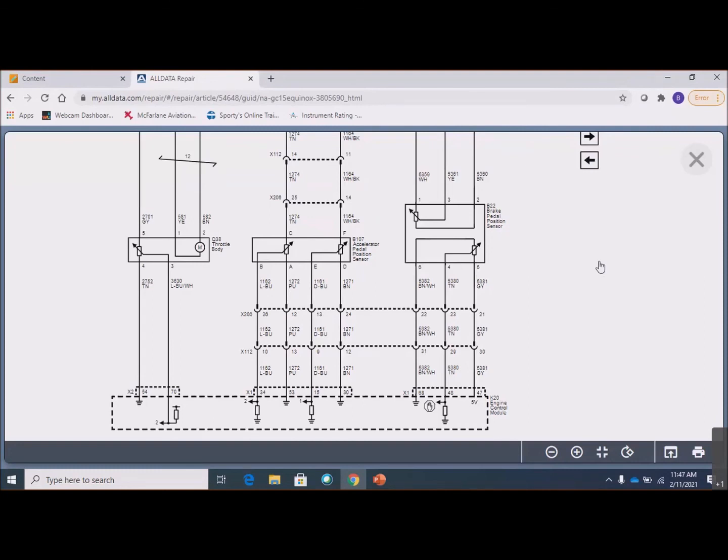It won't do anything. Or maybe if you're the customer, if you're the driver, and this thing goes bad while you're going along the road, maybe you have enough engine RPM to get off to the shoulder of the road, but you can't drive it normally if it loses trust in this sensor. So these are redundant for safety reasons, and if they don't match, then the vehicle will not accelerate.